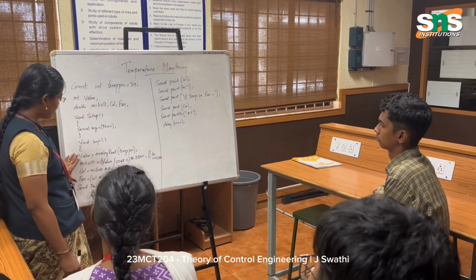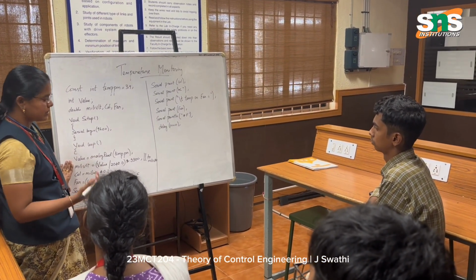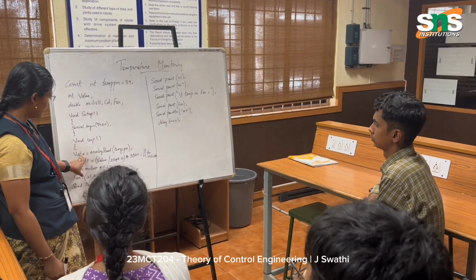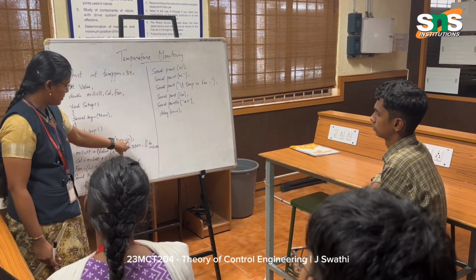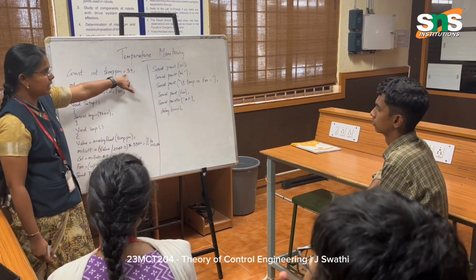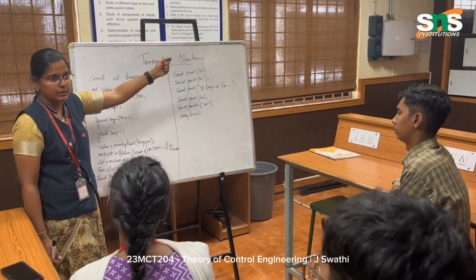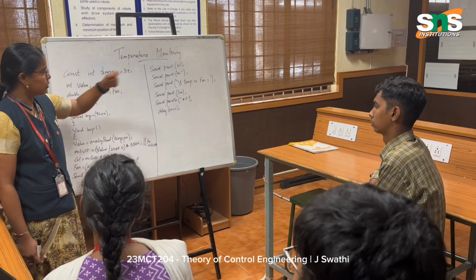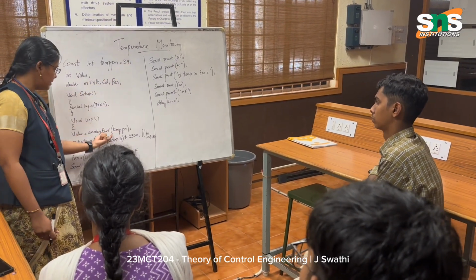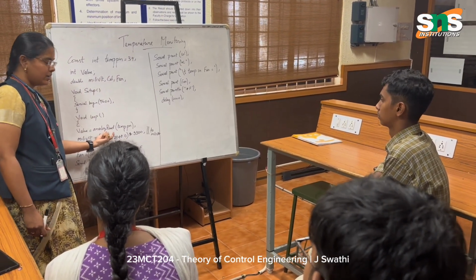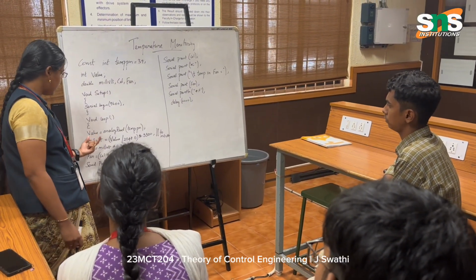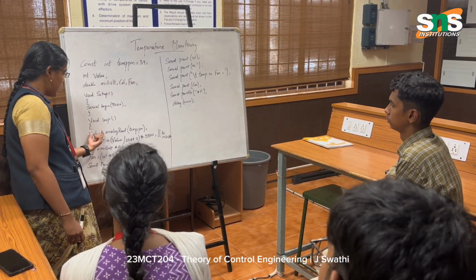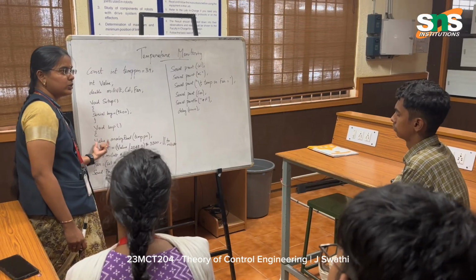In the loop, I am going to add a few instructions like value. This value is nothing but analog read from the temperature pin. From the 39th pin, I am going to read the temperature from the real world. Through this pin 39, I get real world analog data. That analog data will be stored in my value variable. Next, for the millivolt, I am going to convert this value into a voltage value.